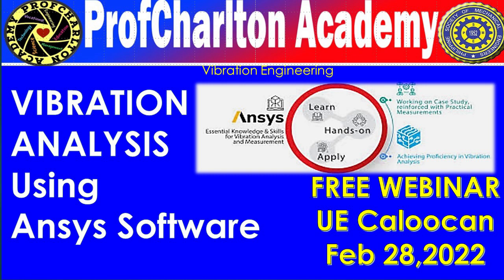So in certain applications, we make use of the natural frequency vibration, and in most scenarios, we try to avoid natural frequency based vibrations, depending upon what type of application we are looking at. That's why modal analysis is fundamental, where you can at least understand all the different modes, mode shapes, and directions.